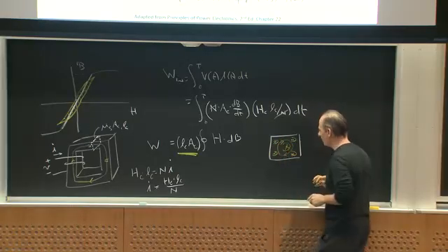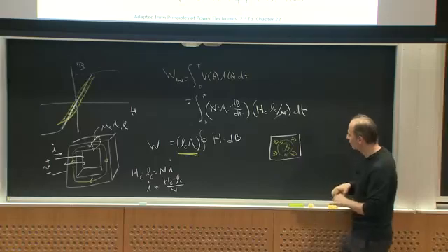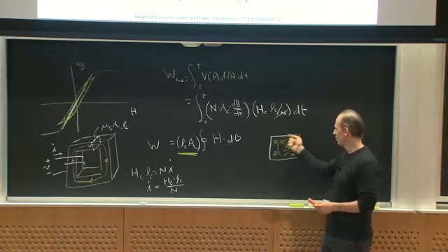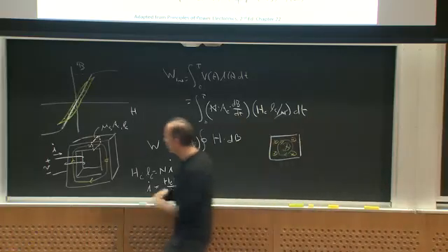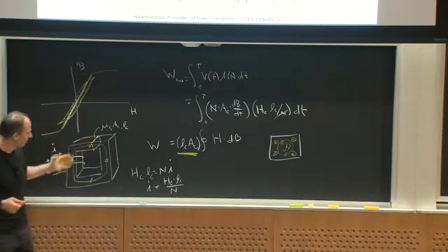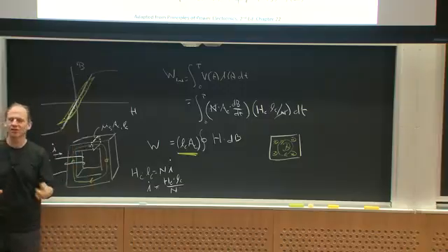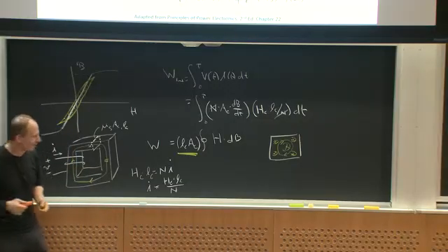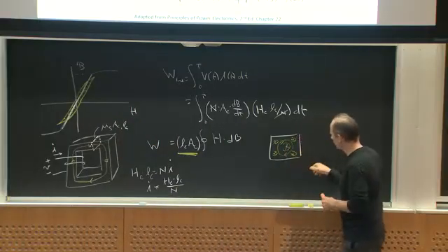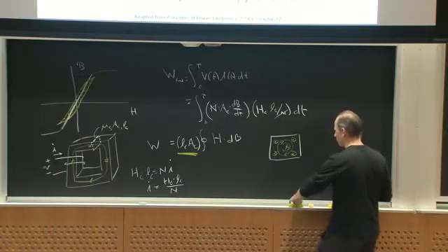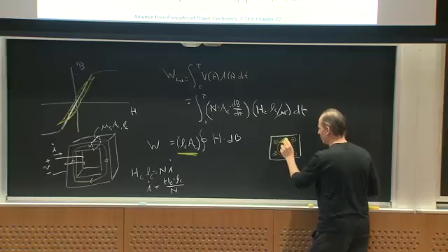And that AC field is then going to generate eddy currents which try to counteract that and reject the flux in the core. Right? So in other words, the fact that I'm carrying AC flux through a conductive material means I can get eddy currents circulating in the core. All right? That's kind of unfortunate. I'm sorry, if I put the flux in the core, the eddy currents are going to circulate this way. Right? So this is I eddy.